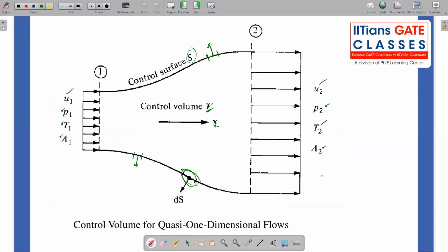What I have for the integral form of the continuity equation is dou by dou t of the volume integral of rho dv, the differential volume dv, plus the closed contour integral, or surface integral, of the flux term, that is rho, the velocity vector v dot the area vector s, so v dot ds.